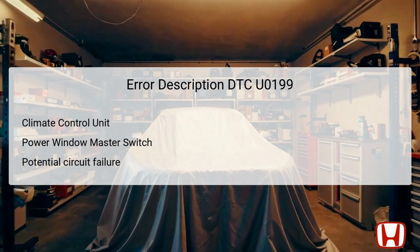When the climate control unit cannot receive necessary data from the power window master switch, it identifies a malfunction and logs this DTC. Commonly, this might happen if the power ground circuit for the switch fails, preventing proper startup. Therefore, before embarking on extensive troubleshooting, it is advisable to check these circuits, as they could be the root of the issue leading to DTC U0199 being recorded.